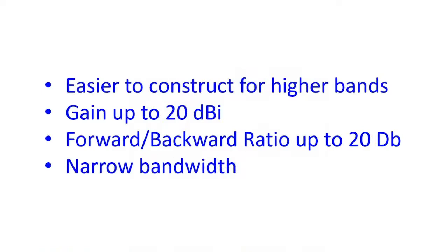Yagi-Uda antenna is often called a beam antenna in amateur radio. Due to the size, it is less often used on HF bands than on VHF and UHF bands. The number of elements practically feasible are also lower on lower bands. They are used with antenna rotators as good directional antennas. Yagi-Uda antennas can have gains up to 20 dBi and a front-to-back ratio of up to 20 dB.